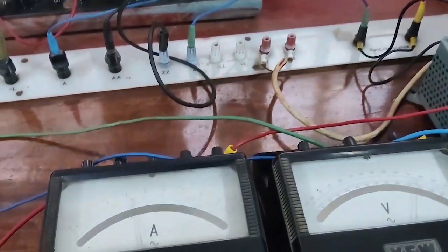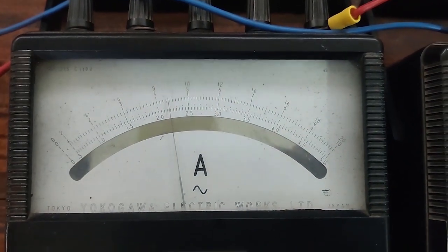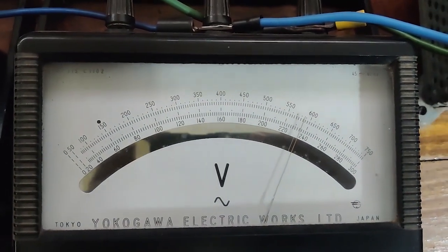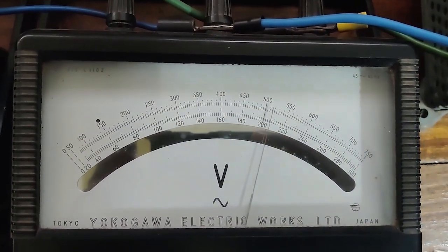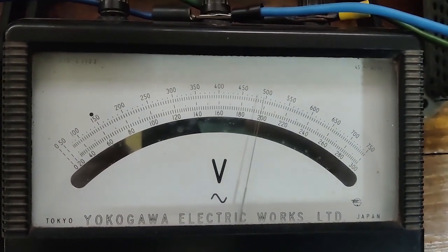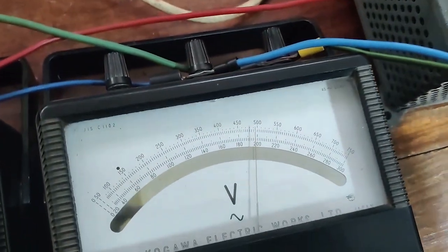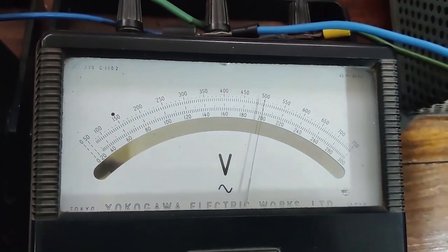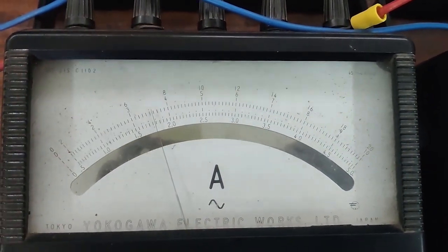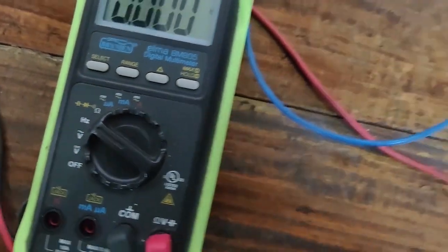Here, we have to drive the prime mover at different speeds such that the no-load line-to-line voltage is within the range of 200 to 280 volts. We have to take magnetizing current, voltage, speed, and frequency readings for different values of voltages. Let's start by adjusting the voltage to 200 volts by using the field current control. And then take the ammeter reading. Now, let's measure the frequency like this and note down its reading.